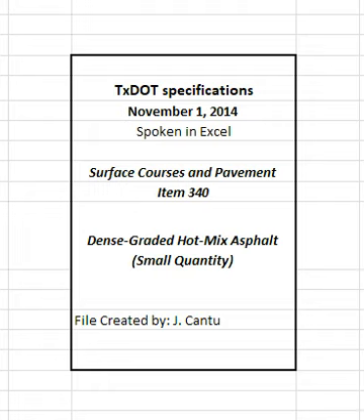Provide the engineer with a mixture design report using the department-provided template. Include the following items in the report: the combined aggregate gradation, source, specific gravity, and percent of each material used. Asphalt binder content and aggregate gradation of RAP and RAS stockpiles. The target laboratory molded density, or end design level when using the SGC. Results of all applicable tests. The mixing and molding temperatures. The signature of the Level 2 person or persons that performed the design. The date the mixture design was performed, and a unique identification number for the mixture design.